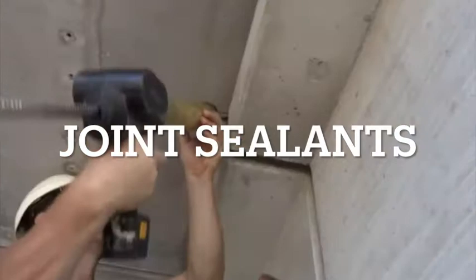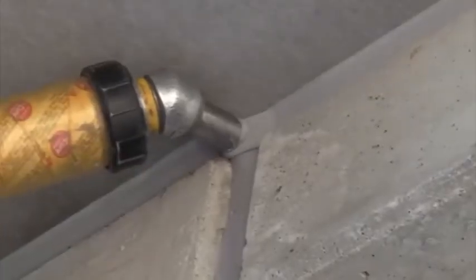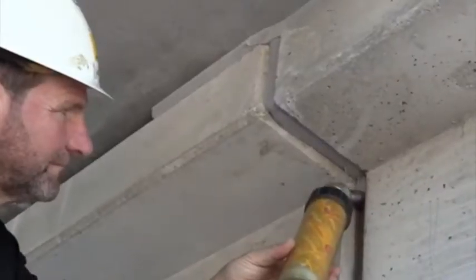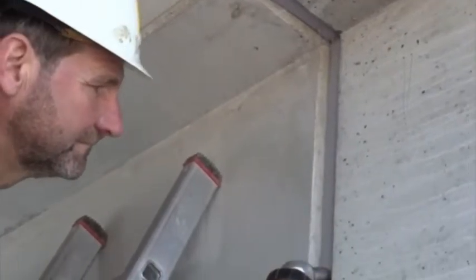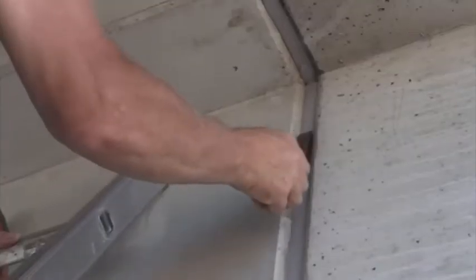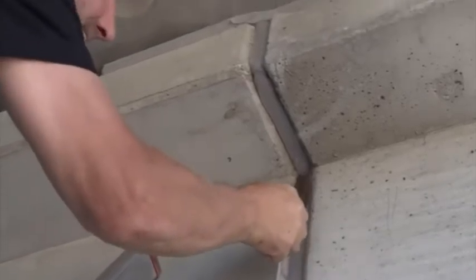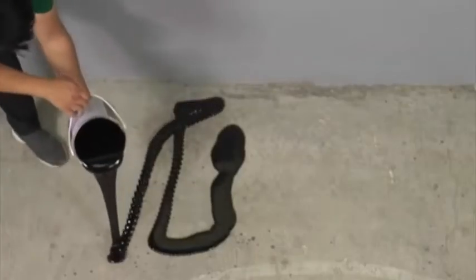Next are the joint sealants. These joint sealants minimize both infiltration of surface water and incompressible material into the joint system. These are used to fill and protect joints between two substrates, sealing gaps and openings. We have two types, the bituminous cement and silicone sealant.